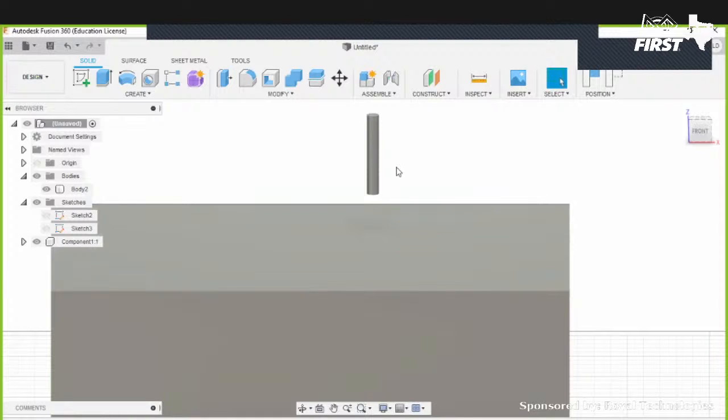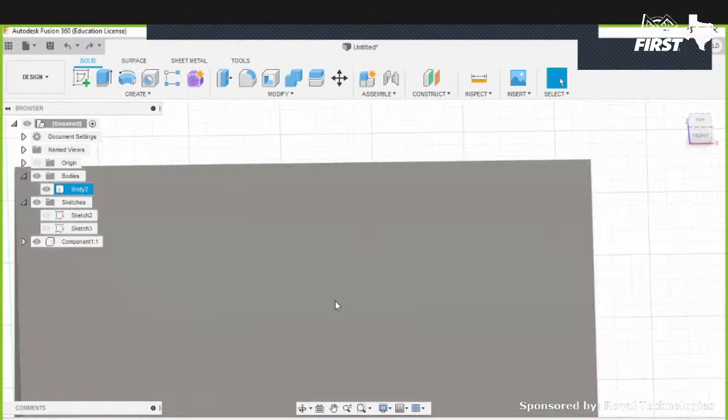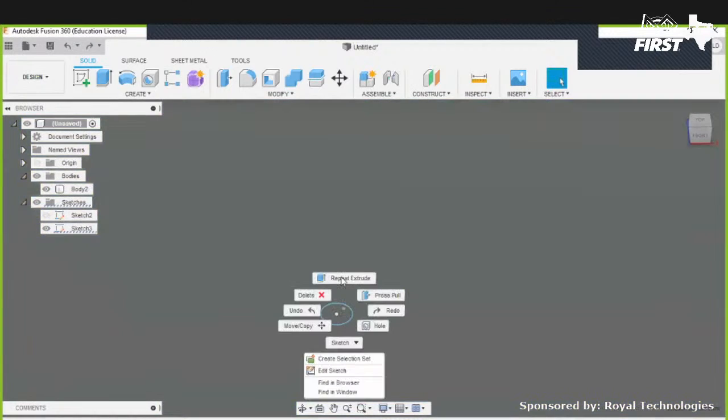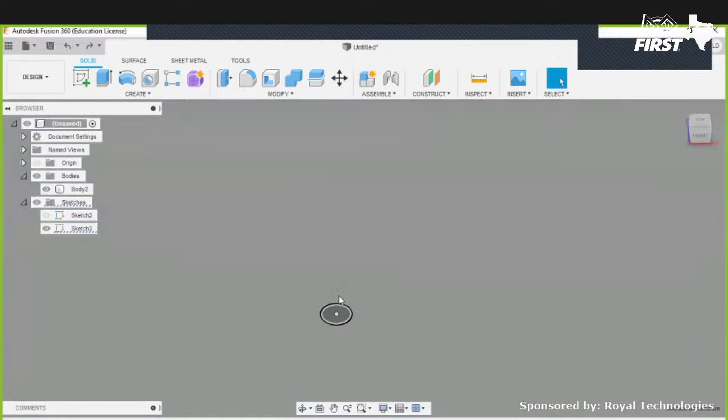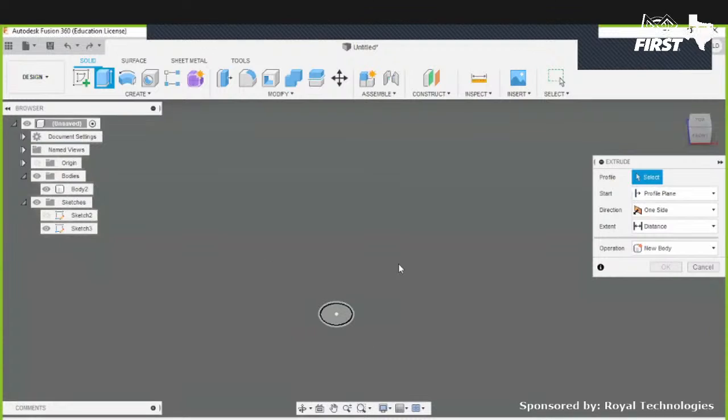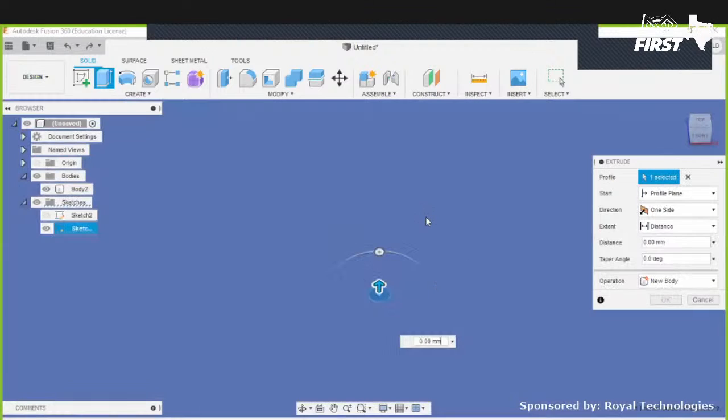Okay, so actually it's an interesting question. If we were to have instead a sketch, oh yeah, look this up. I can right click my sketch and I can click extrude. And so automatically it's going to extrude that one sketch. It's just a convenient tool. Anyways, this is just a question of using a body.